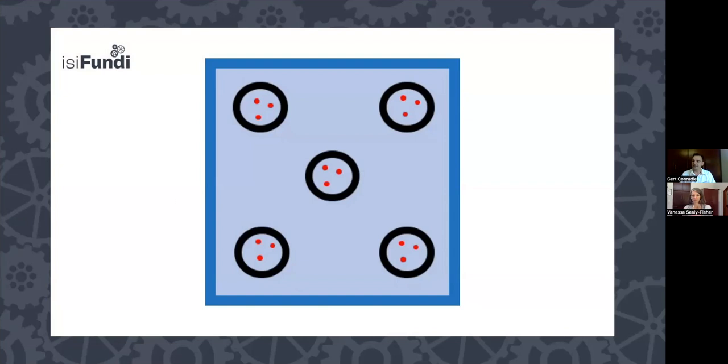single gauge reading. So according to the standard, for every 10 square meters, you will take 5 spot measurements, which are the black circles, but in each spot, you will take 3 gauge readings. And averaging those gauge readings, you get an average per spot. And in averaging the spot measurements, you now get an average for the entire area. Now you evaluate it in accordance with your standard to say, with the specification, am I within what the thickness range was that was specified?